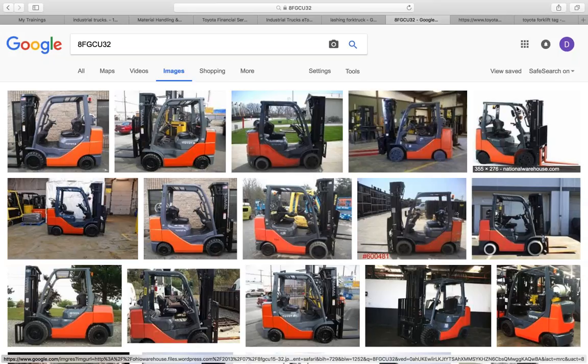And then if you go to page 4, let's talk about falling and flying objects as well. So, different items that we're going to do, right, in order to safeguard against falling and flying objects. We're going to do things like we normally know. We're going to always wear a hard hat. We're going to use toe boards, screens, and guardrails on scaffolds to make sure that we have nothing falling from the scaffolds, right? Basically, practice drops programs or some other type of program like that where we're protecting employees down below from potentially falling hazards.